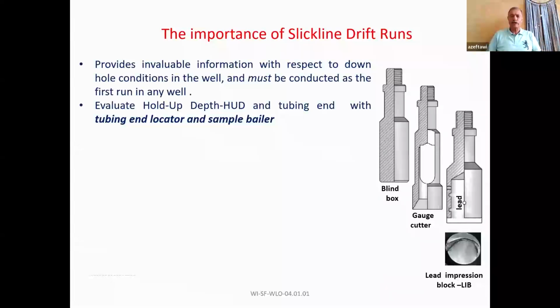I'm in front of the Christmas tree now, and in my experience, I can tell you without any tags on the Christmas tree where is the short and where is the long. But if I didn't find tags on these valves telling me where is the long string and where is the short string, I will not do the job. I will postpone the job and ask them to put tags to clarify which is which. Although I can tell visually, I will not depend on that.